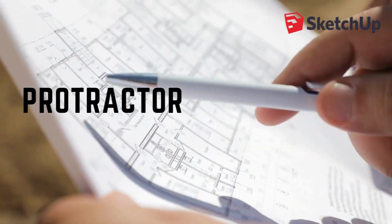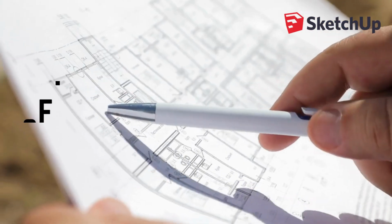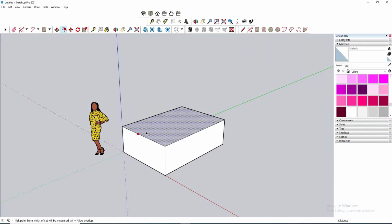This tool has 2 basic purposes: to create angled construction lines and to measure angles. Offset. This tool takes all the edges of a selected face, or a series of connected edges in the same plane, and offsets them.